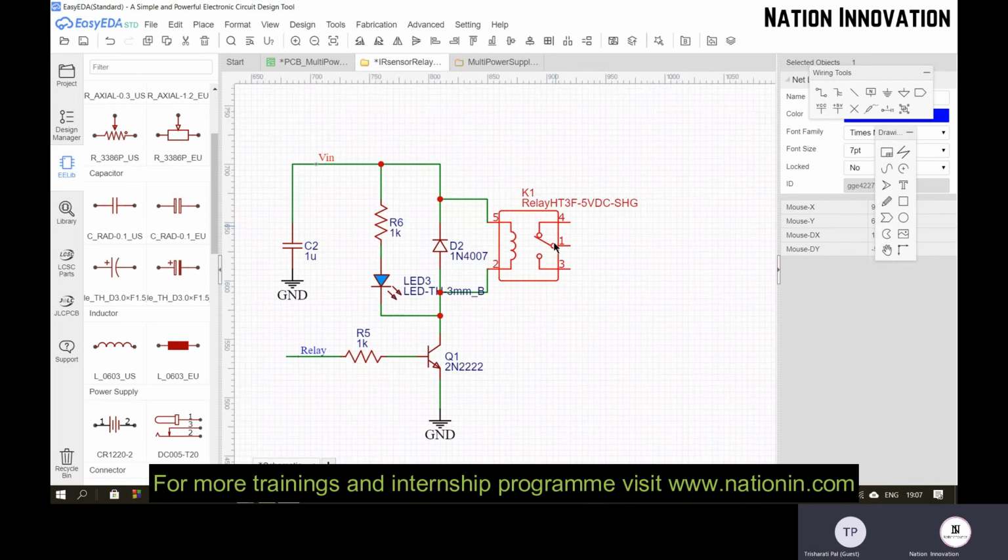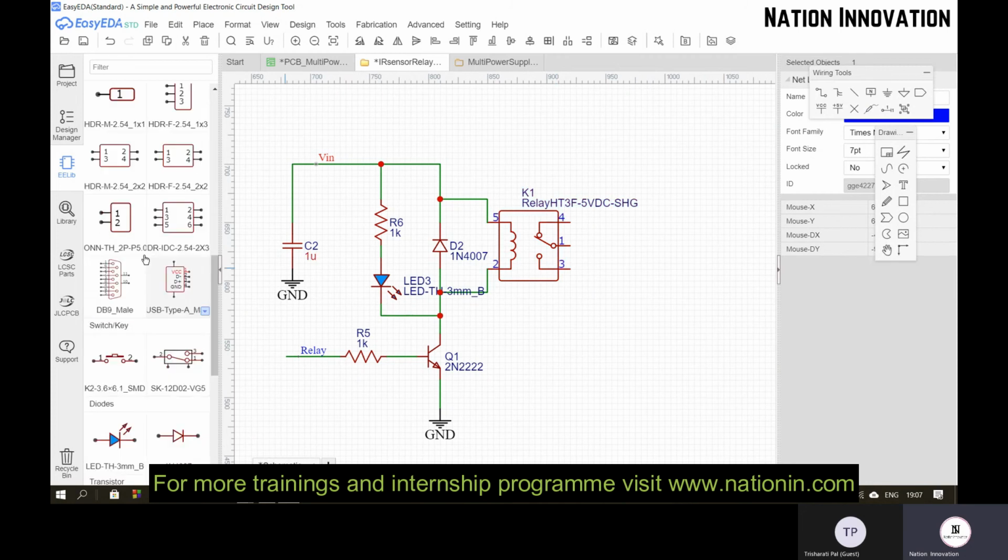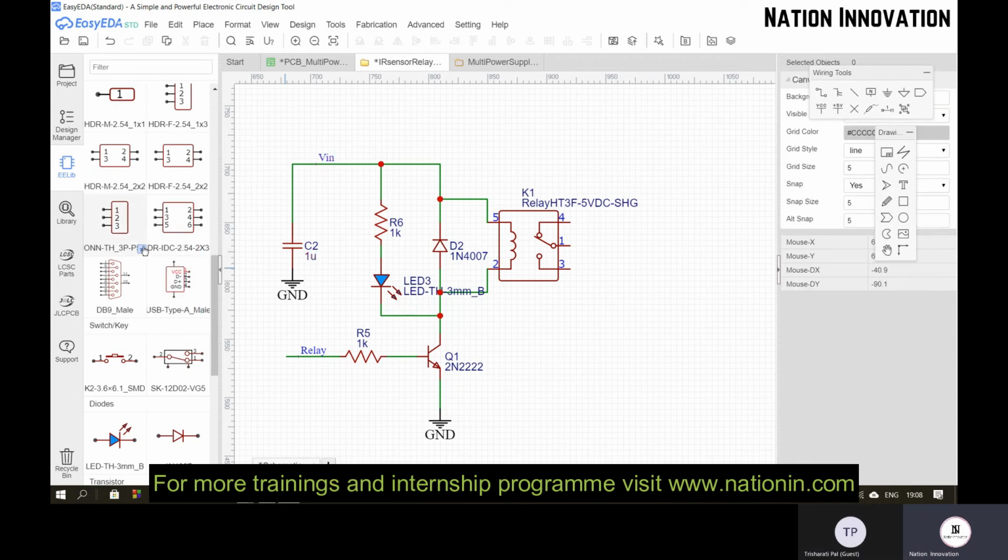Now these are my outputs, the switch relay outputs. I will connect them to a connector. This is a header. HDR indicates header. I need a connector. CONN indicates a connector. So I need a 3-pin connector. You can see here 2P indicates a 2-pin, 3P indicates a 3-pin. So select a 3-pin connector and connect.